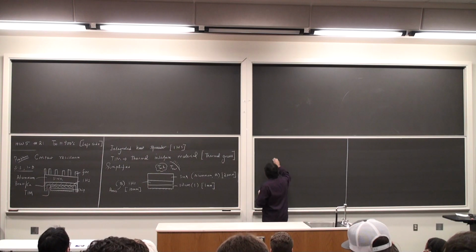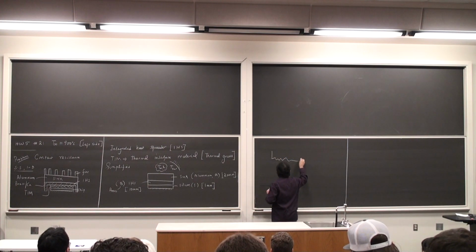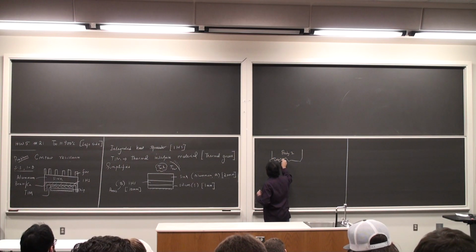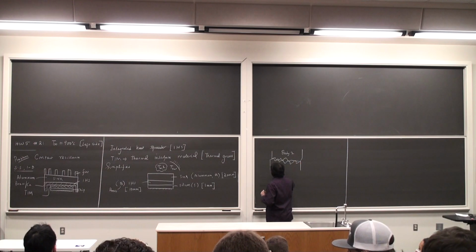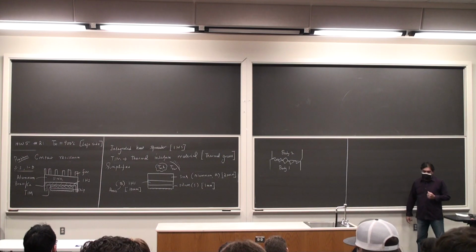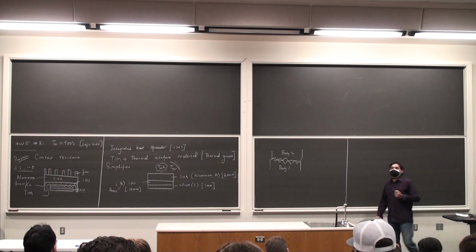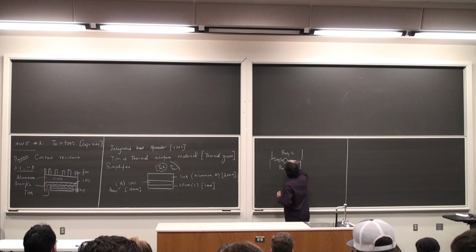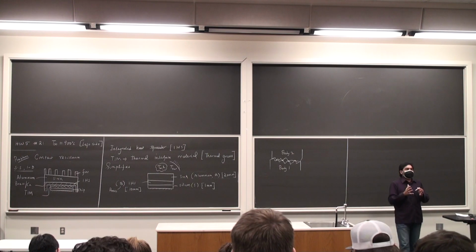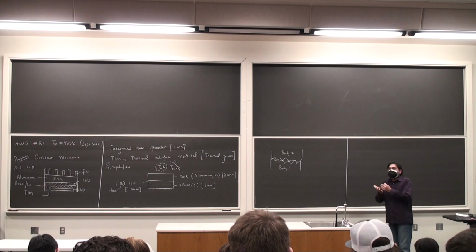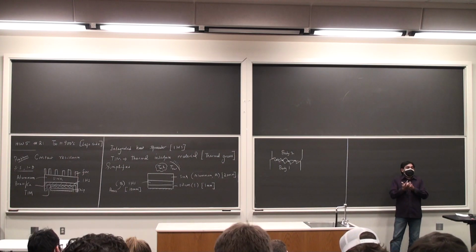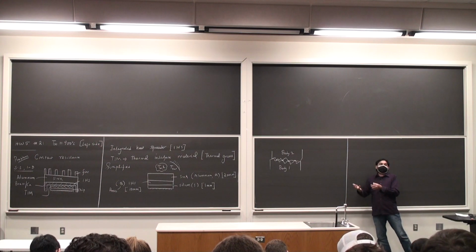Okay, so if I draw two bodies, let's say this is body 2, and this is body 1. Okay, so their contact is going to take place only at the high points of contact, probably here, somewhere there. And so you see that the actual area of contact is really smaller than the interface area that is available to me. And because of this particular fact, I am going to have a temperature gradient at the interface between body 1 and body 2.